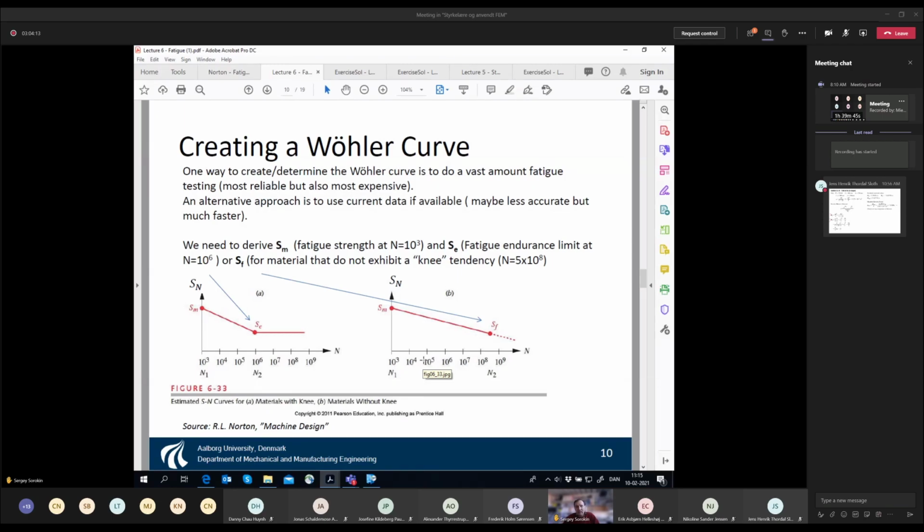But if you start to compare this concept with real life, you may have the damage, this capital C, much less than 1, let's say 0.15. It could be also the fracture, but you may also have a case where this damage equals something like 4, and still there is no failure. So this concept gives you some sort of feeling, but it doesn't guarantee that you'll have the failure exactly at 1.